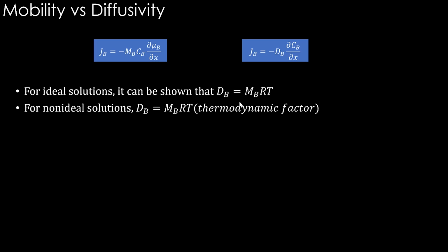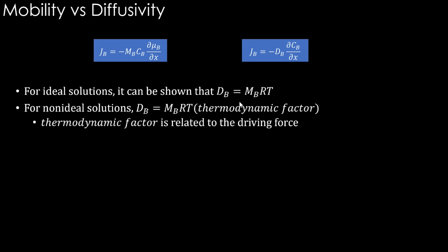What we need is mobility extra, so that we can get the diffusivity. Making a database for actual diffusivity and creating simulations based on that diffusivity, solving Fick's laws, can happen. But the database becomes too difficult to make if we want to make it using only diffusivity. There mobility becomes a very handy thing. That's what we will be seeing in the next class. Let's continue with this now.